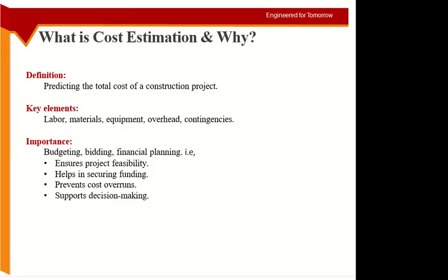Contingencies are events which may happen, so you want to keep an extra amount of cost for those events. These are called contingencies. So if heavy rain happens, I need to cover the site and the concreting, and I have to stop the work, and I may need a pump to get the water out of the excavated pits. So it may happen, it may not happen. So how much cost will I take for this? Contingency is for unforeseen events which may or may not happen. These are extra costs which you may or may not require.